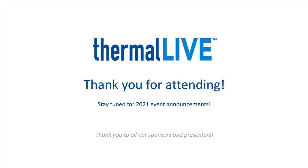So for two-phase cooling, hopefully we gave some examples in our last slide, but basically you can look at both pool boiling and flow boiling, and there's opportunities for foam to help in both. So in pool boiling, you're essentially adding a lot more surface area and a lot more nucleation sites, while also disrupting the film of air, or vapor, that can form near the heated surface. So you delay film boiling.